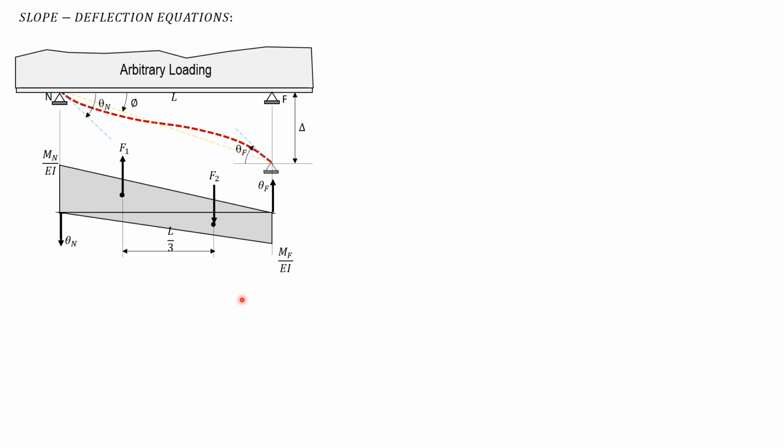So summation of moment about point 2 equals 0. By the way, this is the moment delta, because this delta is downward, negative. The positive moment is supposedly counterclockwise at the right section. Remember smiley bending? At the left side clockwise, at the right side counterclockwise. But because this is negative, the moment is clockwise, delta, at the right end.